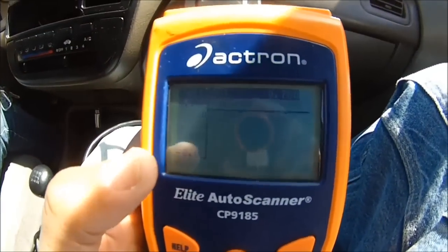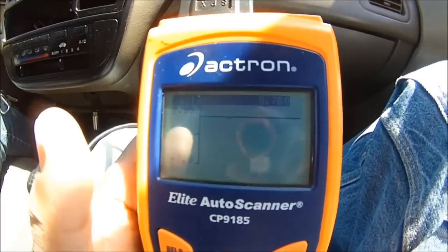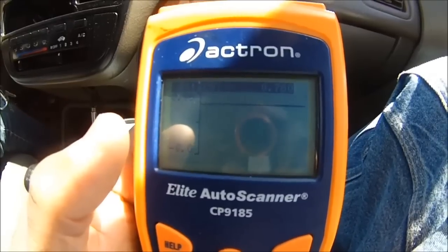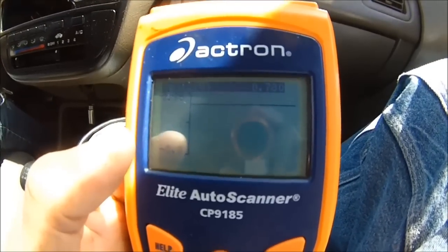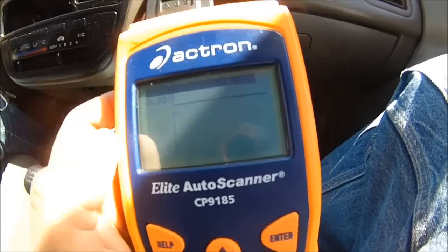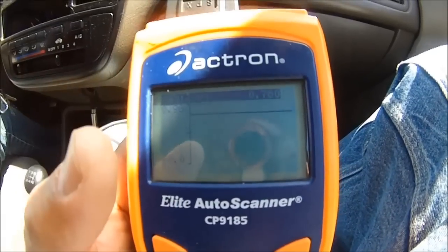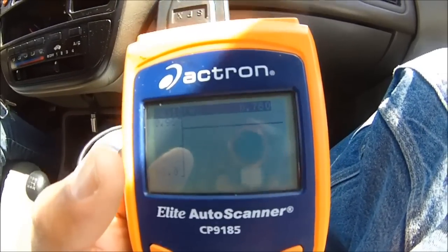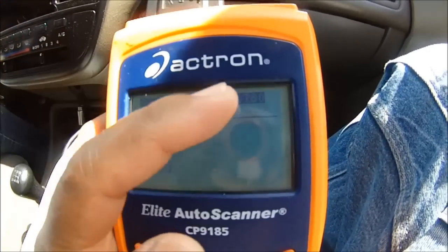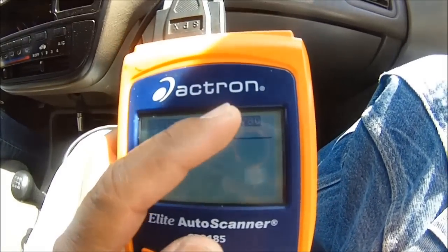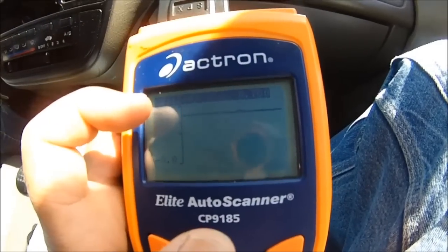Okay, this is the downstream O2 sensor. On this vehicle, we've got 780 millivolts. On the other video I showed you earlier in this video, that car was reading 450 millivolts, which was right here in the center, okay? 450 millivolts is normally 14.7 to 1, stoichiometric air-fuel ratio. This one's high, 780. Some technicians like that high number, some like it right at 450 millivolts.